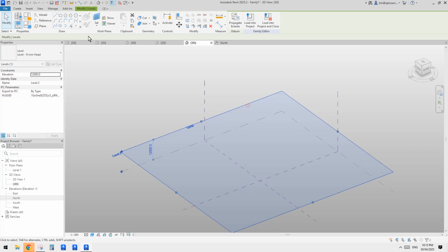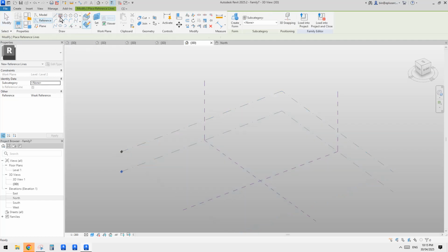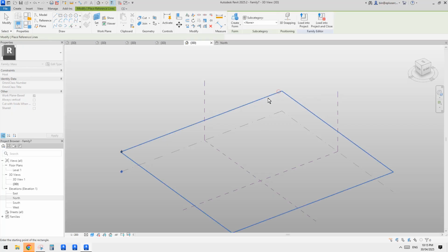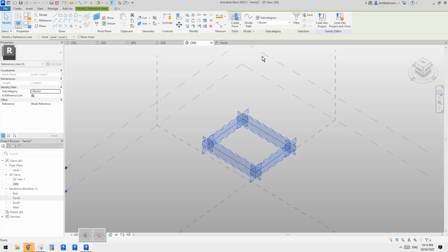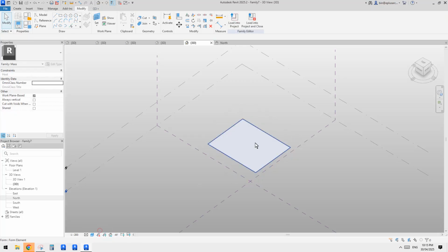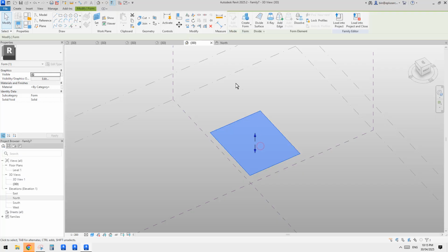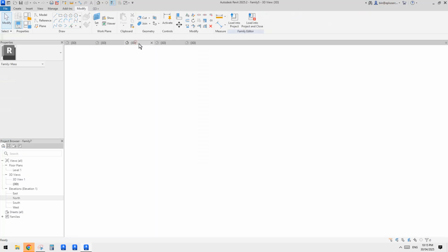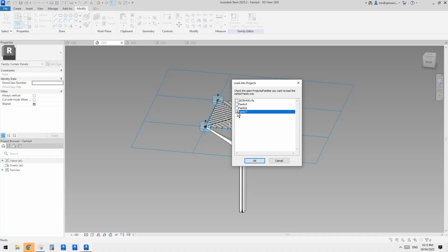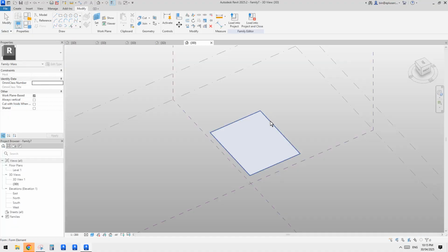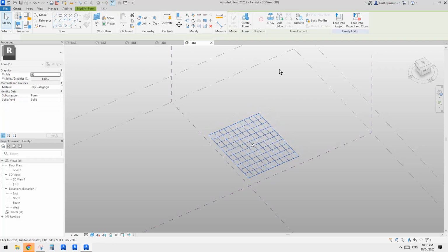So we can just place a shape, rectangular, draw a work plane, set work plane. We can pick the level. I'll just do something like this, okay? And then select it, create a form. We only need a surface, so that's it. And select it. Actually, let's load that family in family 4. Load it into family 7, which is the conceptual mass, and divided surface.